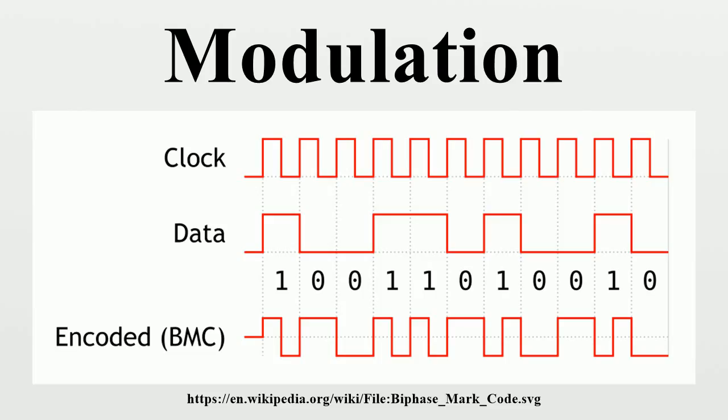OFDM is considered a modulation technique rather than a multiplex technique, since it transfers one bit stream over one communication channel using one sequence of so-called OFDM symbols. OFDM can be extended to multi-user channel access methods in orthogonal frequency division multiple access and multi-carrier code division multiple access schemes, allowing several users to share the same physical medium by giving different subcarriers or spreading codes to different users.